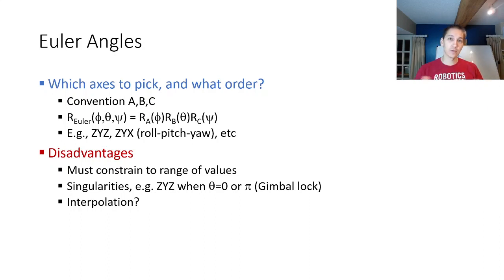So this is known as gimbal lock because there's a mechanical structure called the gimbal that has been used in aerospace for a long time to figure out the attitude and the roll, pitch, and yaw angles of an aircraft. Basically you use a gyroscope with this kind of mechanical device. And when the angles of this device ended up lining up, then it would actually get locked in place, and the inertial effects of moving around didn't unlock it. And so this problem had to be dealt with by other means.